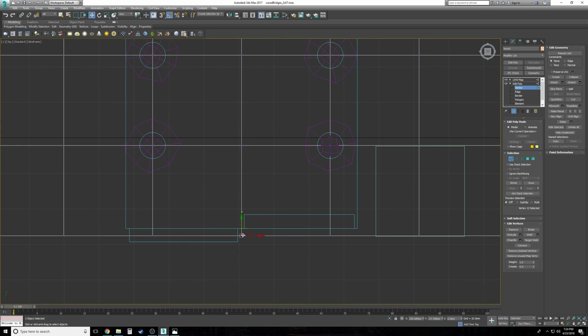And if you have just these selected and ignore the vertices here and there, then this thing will shift, and all of a sudden this female end will have a much bigger gap than this, and this will shorten. So you've got to select the vertice here, where you're wanting to go.